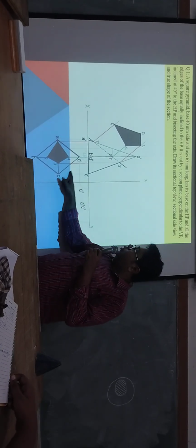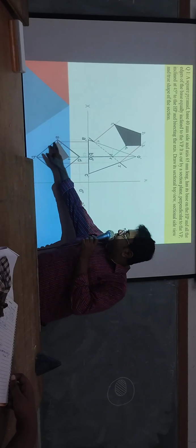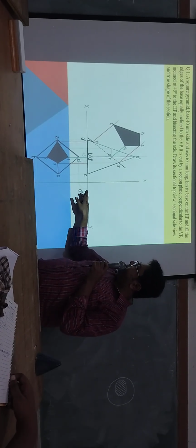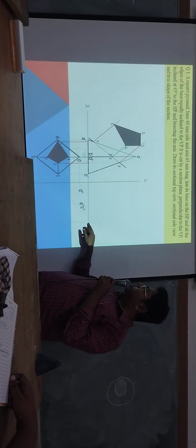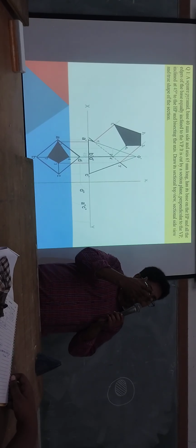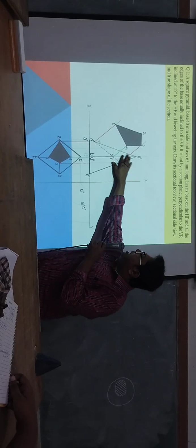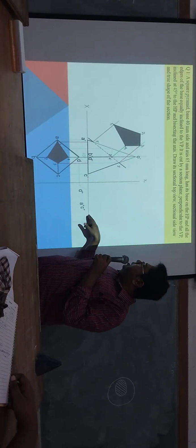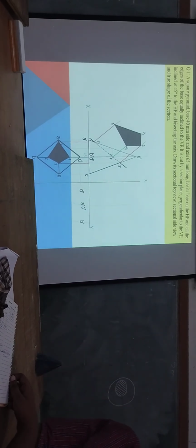You will take the main component. It was actually rhombus, right, in top view. So you take the rhombus, you project it. So D point means you are projecting here, AC means you are projecting over here, this is B means you are projecting over here. Simply draw the side views. All of you know in assignment 2 the same process. Now from here what you will do? Simply you will draw the horizontal lines, to complete the triangle in the side view.